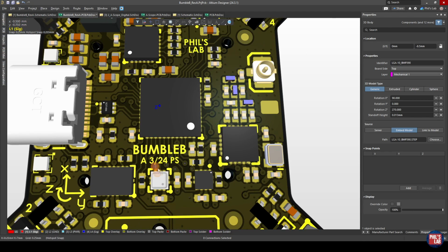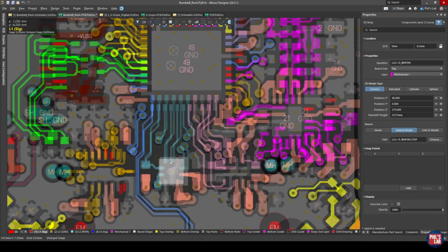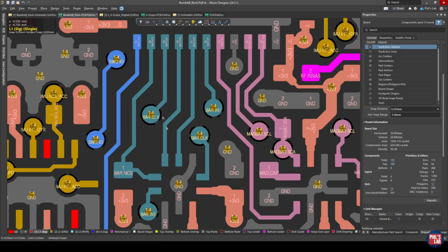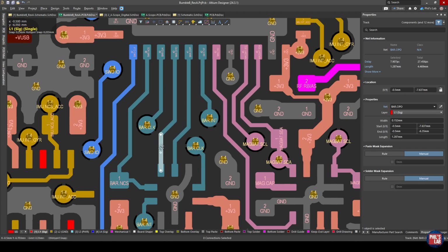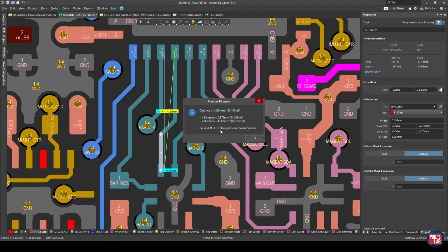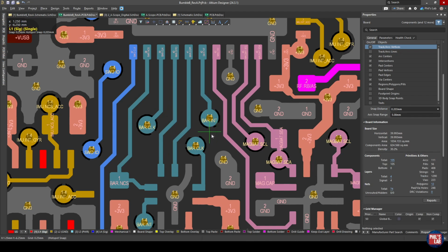I try to place that as close as feasible so I can fit in all of my other components, of course, but not further than I needed to. This meant also rotating the component and selecting the right pin out on my microcontroller, so that I simply can have pretty much a straight connection between these two interfaces. So trying to keep my connections as short as possible. You can see here they're only a couple of millimeters, so termination definitely not needed.